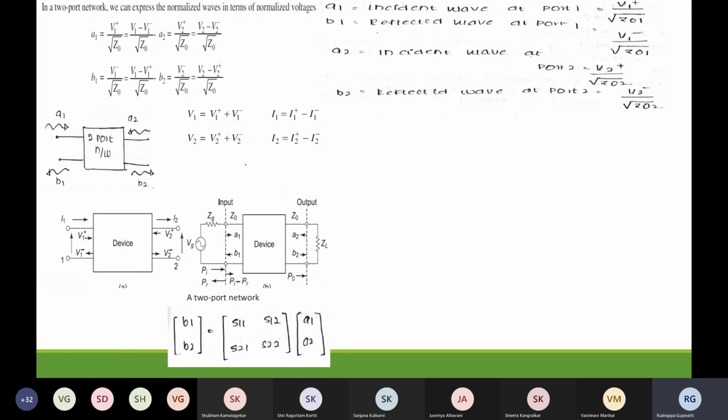In a similar way, we can obtain the S matrix, in which we obtain the association of the reflected wave amplitudes with respect to the incident wave amplitudes. So these two are associated with the help of the S matrices or the scattering parameters. So how do we go ahead? We can observe the equation in matrix form, which is present over here.